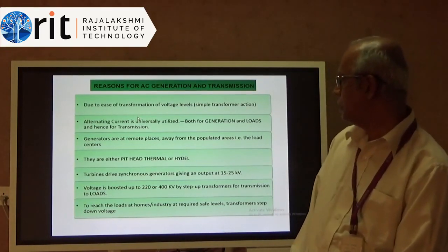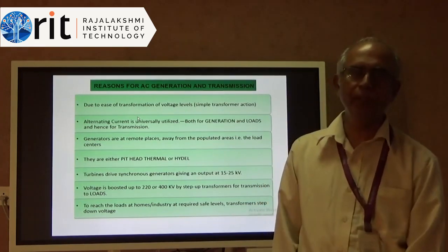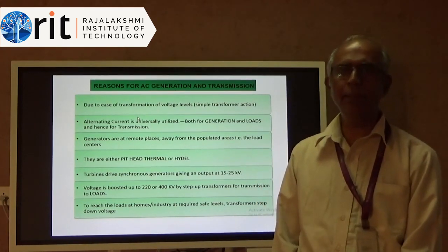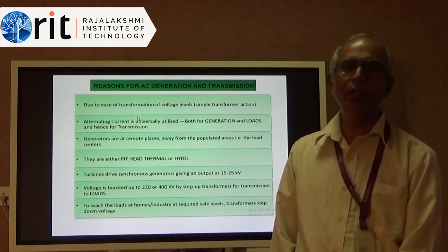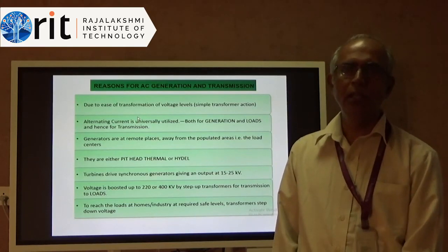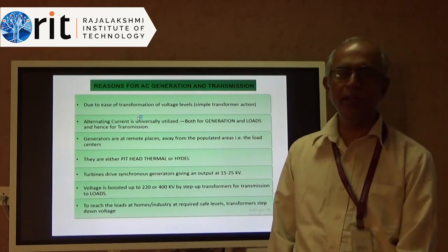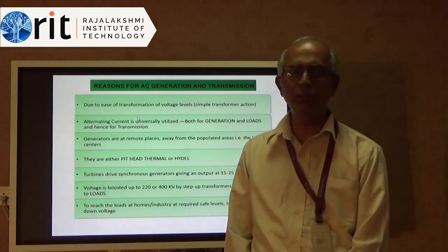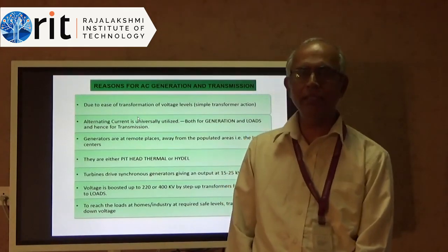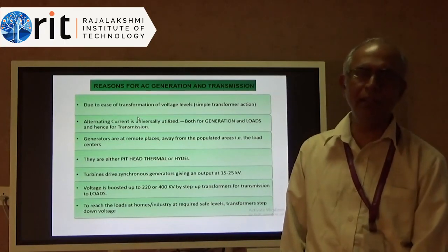So generation is done at a remote place away from the populated areas, that is the load center. Right? If generation could happen right in our campus, then we wouldn't have this difficulty of transmitting at a high voltage and stepping it down. But unfortunately that doesn't happen. Generation takes place where you have the necessary fuel available. Suppose coal is available somewhere, it makes sense to put a coal power plant near the coal, where the availability of coal is there.